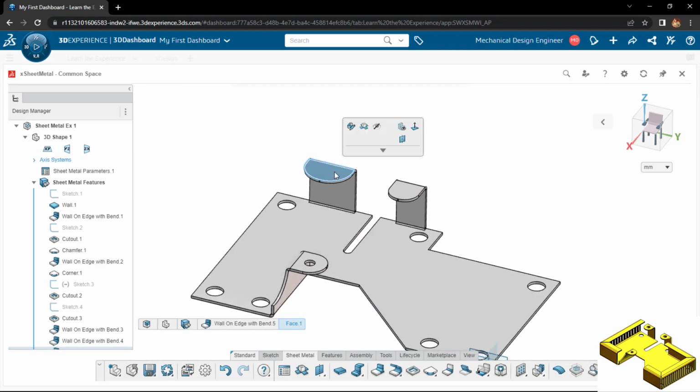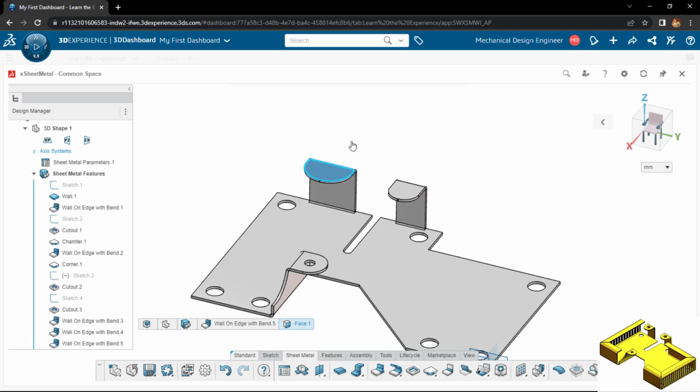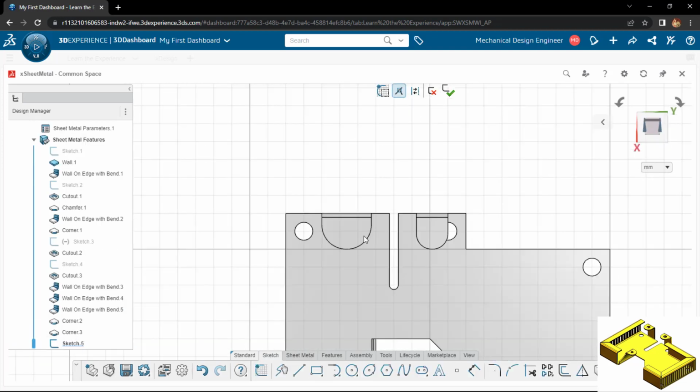Yeah, so on these I need to add the holes for the fasteners to fit. I don't want to place exactly at the snap location, so I'll take this snap location as a reference and I'll make it horizontal, this point and this point, and still underdefined.